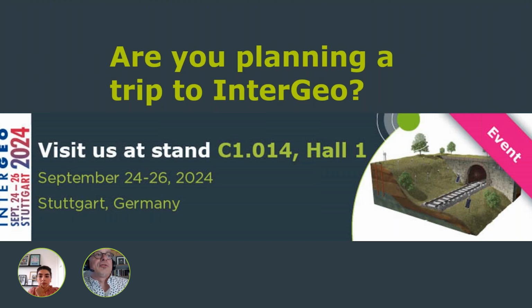So absolute measurements, like, for example, if you put a GNSS receiver on top of an object where you have an absolute coordinate, no, we can't do that. We have no sensor or device that measures absolute position. But I would consider that even if you do it with a total station or with a GNSS device, you would actually be interested in the displacements, and that's always a relative value. Okay.